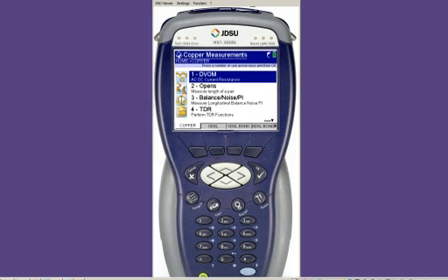So that may be something that you should consider. The new battery's charge port is on the battery itself. It's a round barrel connector, male-female arrangement. There are 2 LED lights there. Red means it's taking a charge. Green means it's fully charged. And finally, the round hole between the charge port and the LEDs is a serial port.